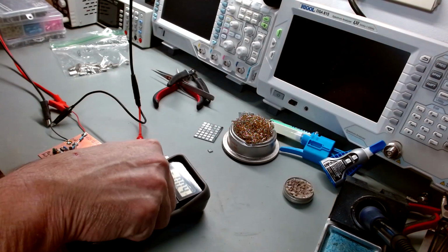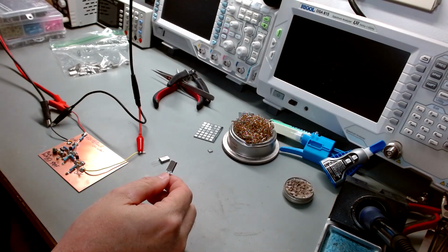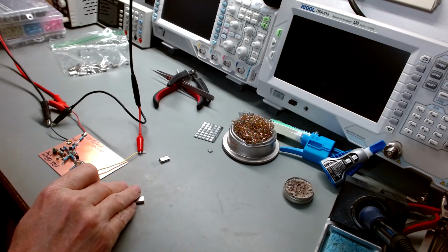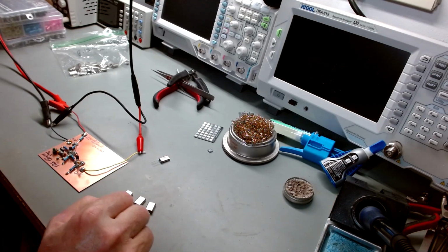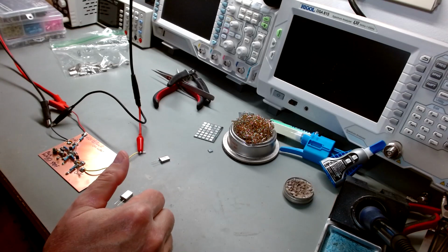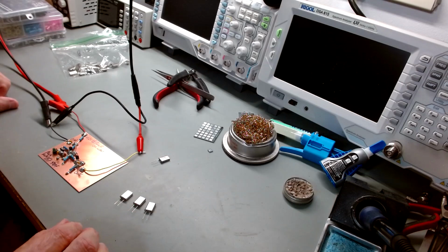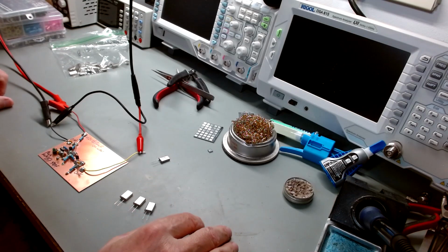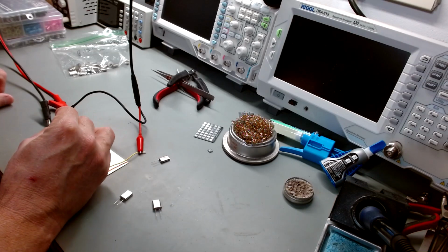That's not exactly what it is. Of course, I have the big LCR meter, and it reads this as about 4.7. Some of these are 4.3 and 4. I find that most of these crystals in this format run somewhere around 4.5. If you just had to guess, I would go with 4.5 picofarad and run with that and see how you turned out. Can't guarantee you to be perfectly accurate, but it'll put you in a ballpark.